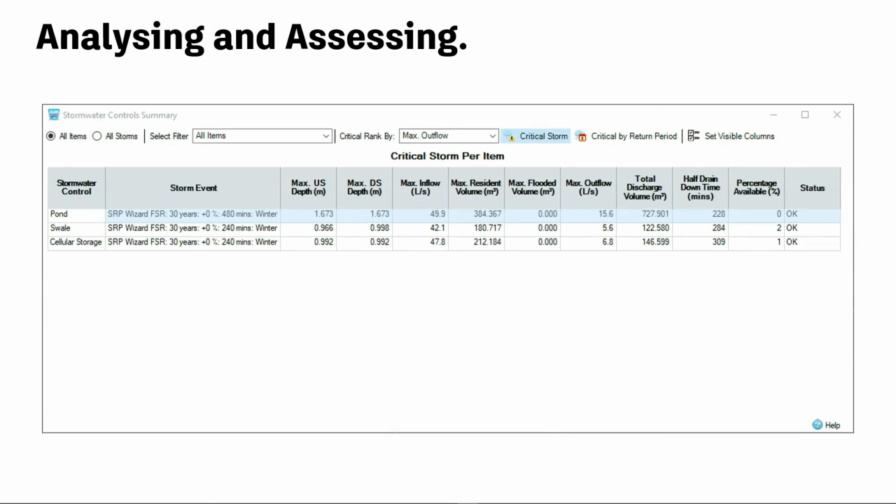For example, in Scotland, it is required to test drainage networks for 200-year return period storm events. By simulating these storm events, we can make further changes to the network and fine-tune the system until it is described as optimized. Once optimized, the result outputs can be generated into a report to submit as part of a drainage application.